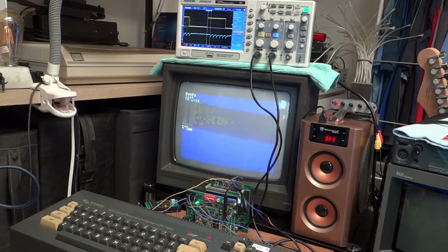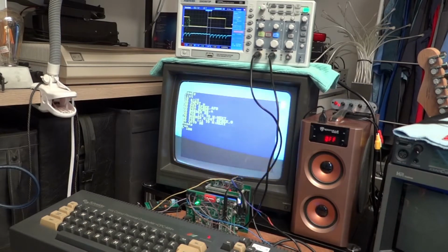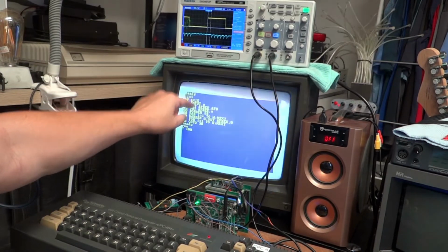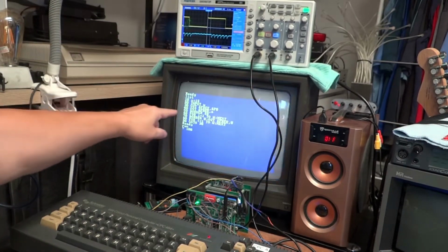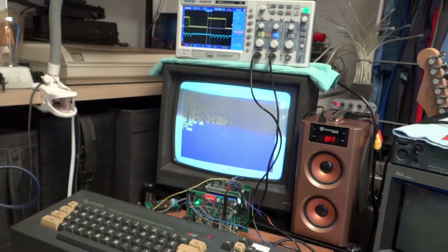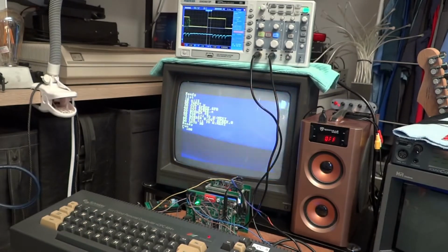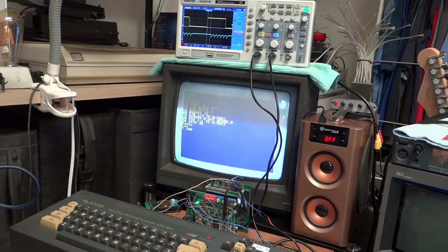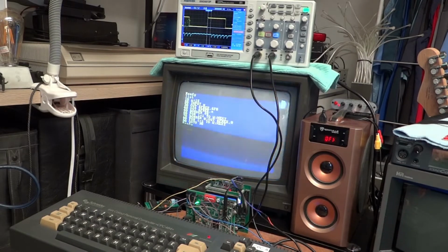But then another 5 milliseconds are caused simply by the BASIC program, because there's a delay between the OUT statements that trigger the channel 1 digital signal and the change in border color. So that's another 5 millisecond delay. This is our baseline, so it's safe to say it's like 5 milliseconds of delay for a CRT.